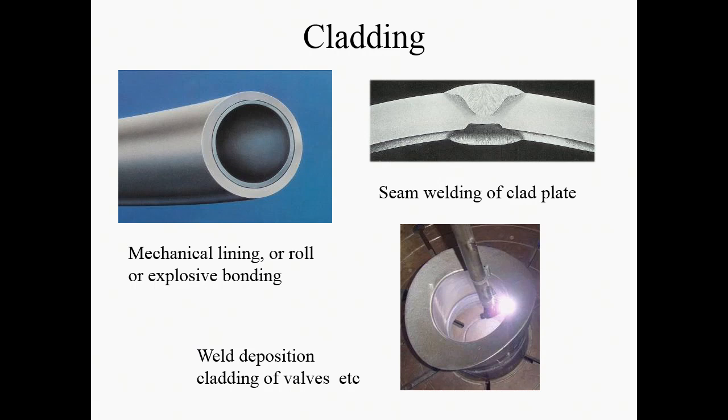That's usually done for fittings, for valves and things like that, because the direction of travel and the time it takes to actually do the coating is very low. For long joints, you usually use these sheet manufacturing methods. And the problem is that you have to then seam weld a corrosion-resistant alloy. So you'll have a different welding process on the inside and on the outside of the pipe, and it just makes things a bit more complicated.